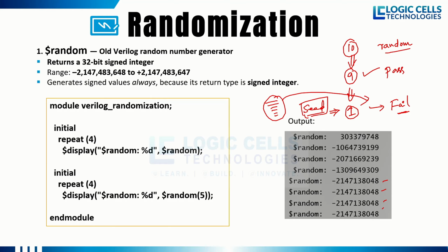You need to identify why my design is failing for these kinds of values only. 90% of the time it is passing. Then this is your corner case. Some corner case of your design got hit. It is not so well developed or designed. So you need this seed value. For this random set of values, let's say the seed number is 256, or 1025, something like this.